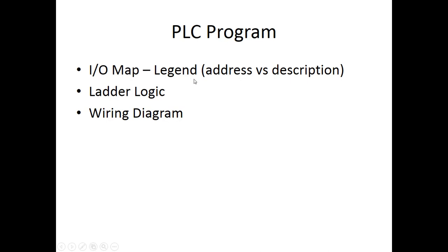You want to have your ladder logic documented. So for that input, I:1/1, for example, you want to label it as PB1. And then you want to label the rungs, or a group of rungs if they're performing an operation, such as these next 4 rungs blink a light, you would label that. That would be really useful for somebody who was troubleshooting.